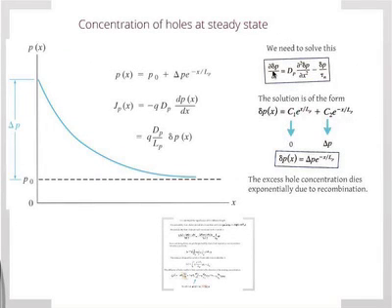So let's concentrate here for the time being. Okay, so we need to solve this equation. This is the diffusion equation we just looked at. Change in concentration of the excess carriers as a function of time is given by the diffusion coefficient times the second derivative with respect to space minus the recombination rate.